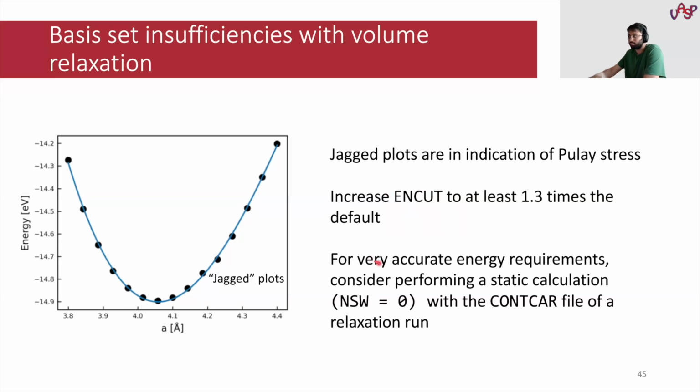Another thing to mention is that if you're after very accurate energies, please do consider running a static calculation with NSW=0 with the CONTCAR generated after relaxation. This helps. There's a lot of documentation about this on our wiki. I highly recommend taking a look as we go along. There's a lot more information and examples, but I think these are a couple of caveats that I thought I'd mention, perhaps out of context, but something that you could stumble upon very quickly.